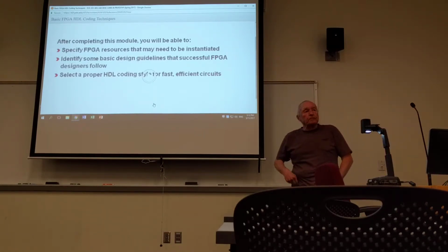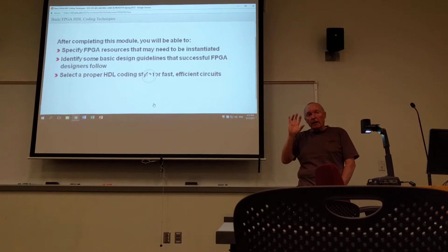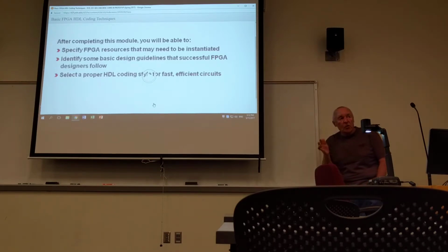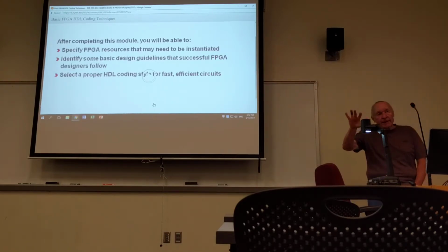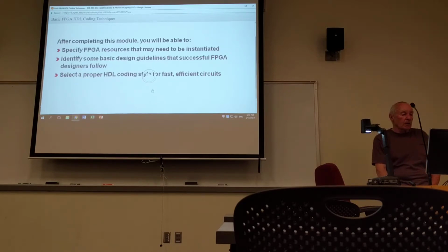Core Generator is a design automation tool they have that gives you access to their library of components. So their second party IP. It's got a search engine and all of that stuff, so you can say, I want this particular type of circuit. You can configure it any way you want to, and then it generates the module along with a file that will tell you how you would instantiate it into your design. So Core Generator is just their GUI that gives you access into their component library.